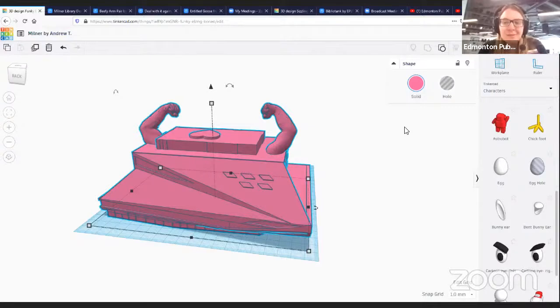And this creates a lot of problems for 3D printers, because especially the kinds of 3D printers that we work with, they don't necessarily catch on. The software is very good, but if you send an object that has a big hole in a part of it, the 3D printer doesn't know that you've made a mistake, so it will do its best to carry out your command essentially. And sometimes you can end up with failed 3D prints. We sometimes call them 3D spaghetti, huge bird's nests of filament, because a piece of filament has been dropped and then each successive piece of filament has been dropped after that.